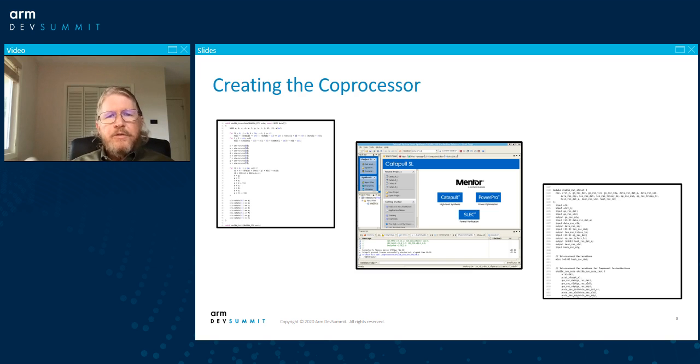And with those modifications, and identifying loops that we were going to unroll and some pipelines that we were going to create in the hardware, I ran it through Mentor's Catapult high-level synthesis tool. This generated a block of synthesizable Verilog that represented that same function that was described in our algorithm in C++. So this has the exact same functionality, but now it is at a level where we can feed it to an RTL synthesis compiler for gate level implementation and layout.